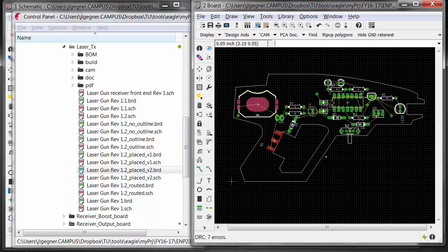So I'm going to need to follow this up with basically creating Gerber files by running the CAM processor, and then submitting that to the free DFM online. And then generating the different PDF views. So I plan on making a video to just show you that, but that should be much shorter than this first one. So, all right, hopefully this will be helpful to you, and that's all for now.